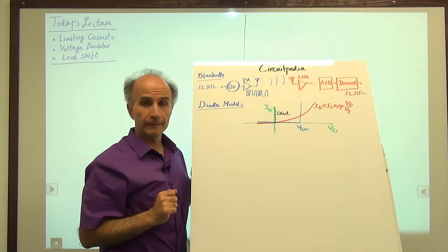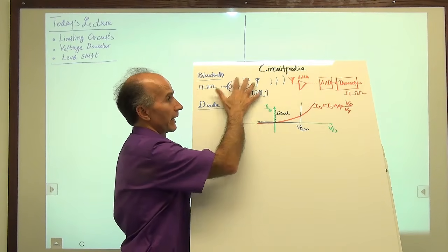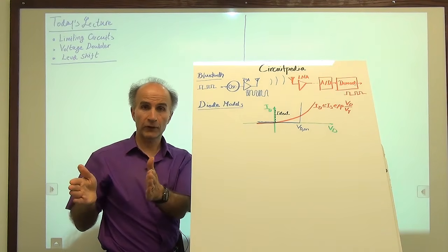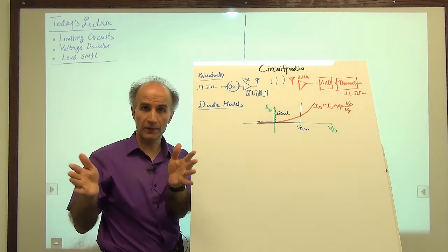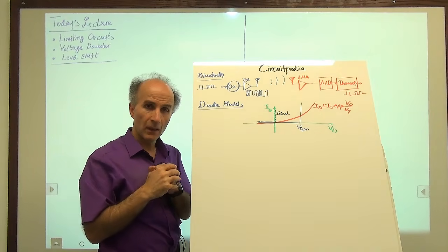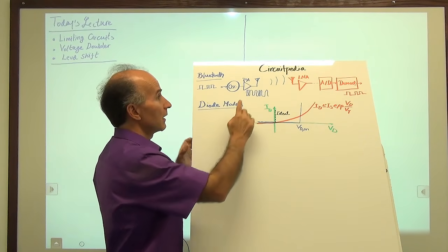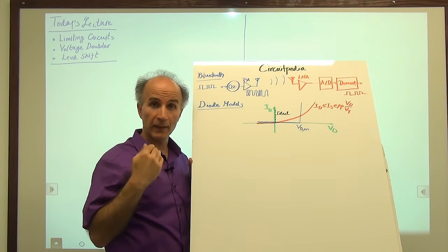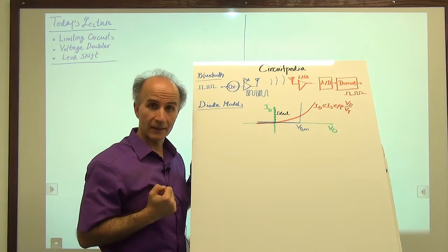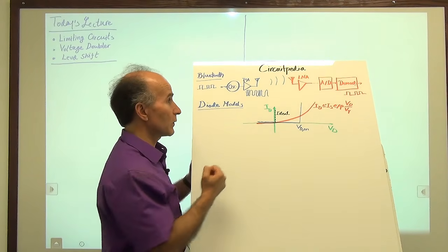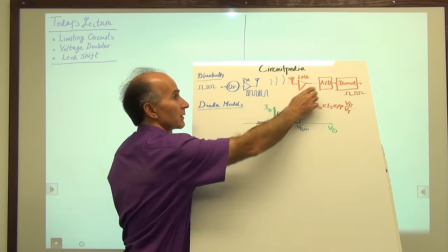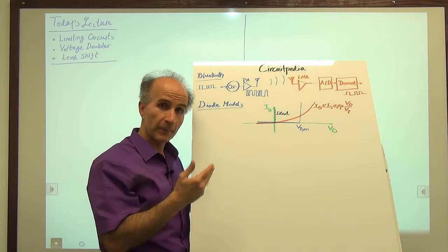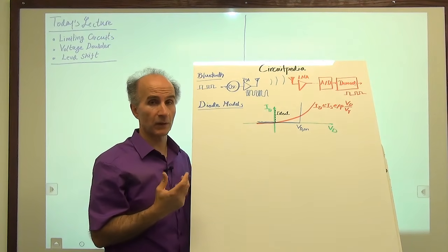Now the question is, if the laptop and the printer are very close to each other, so let's say they're just a foot apart, about 20 centimeters or 30 centimeters apart, then the signal that goes from the transmitter to the receiver is very strong. It has not been attenuated over a long distance. So if it is so strong, what happens to it here? What does it do to the circuitry here? It may cause problems in these circuits because the input signal is so strong.